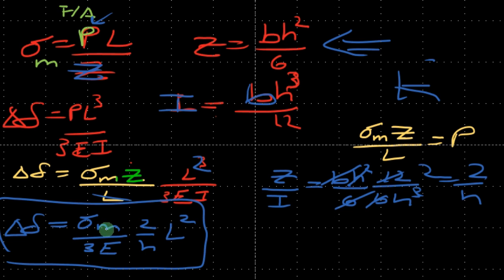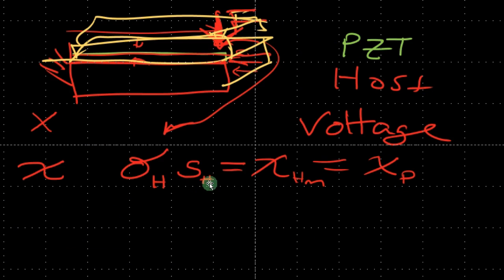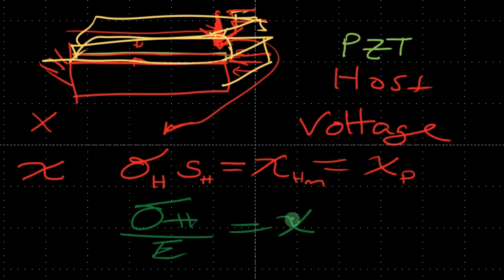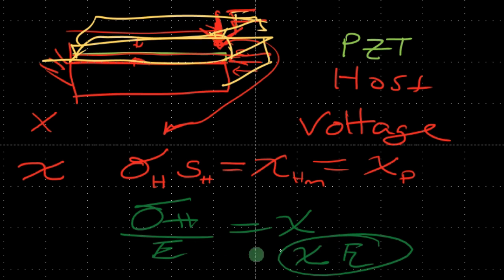So we're taking the stress, and then we're going to try to get to strain. So what's the stress and strain relationship? We saw before here. Stress times the compliance equals strain, or we can just write stress divided by the elastic modulus equals the strain. So we want to get that strain. So we divide. So basically, we have the multiplication of these two equals the stress.